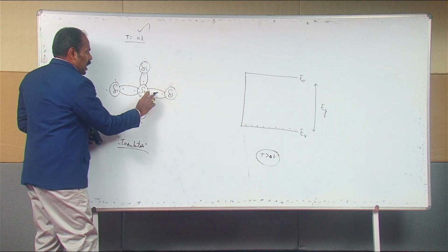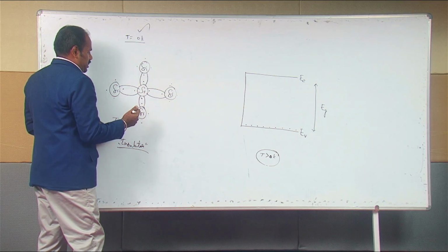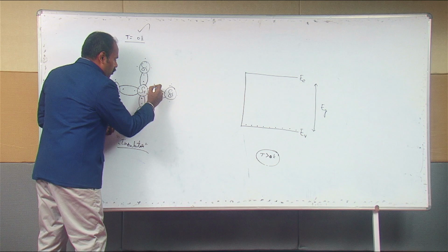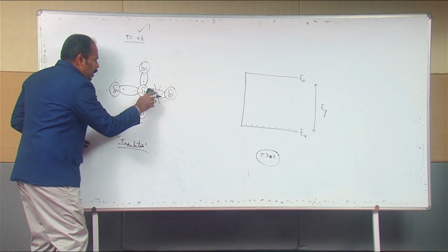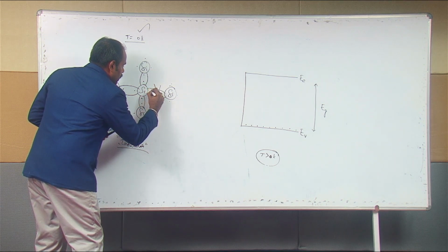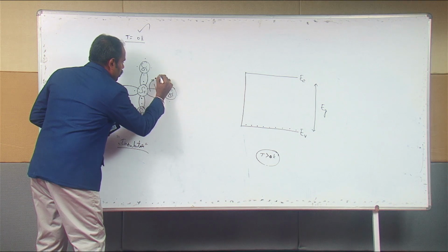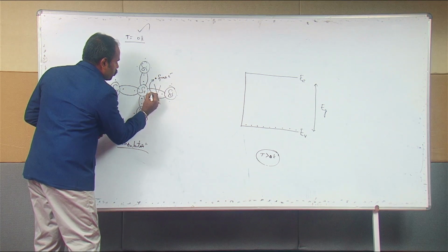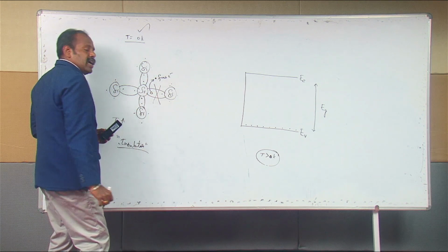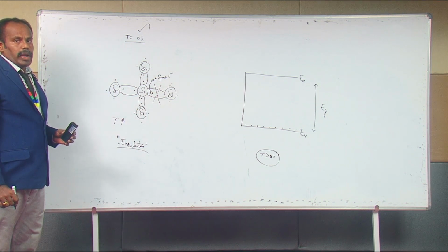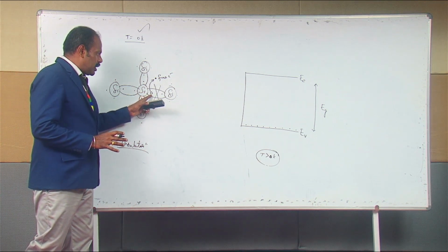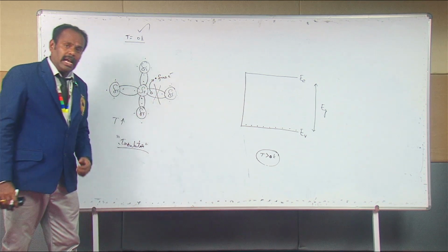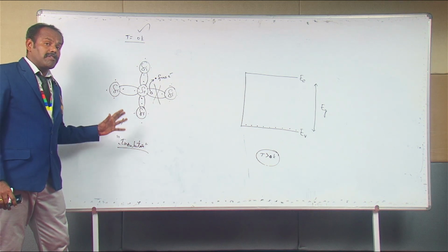Let's suppose that this particular electron is gaining energy, and as this electron gains energy, this covalent bond gets broken. When the covalent bond gets broken, it simply means that this electron is set out as a free electron. Now it is becoming free. And when an electron becomes free, correspondingly a hole is created at the initial electron's place. So a hole has been created, and a free electron is being introduced into the system because of the influence of the temperature.